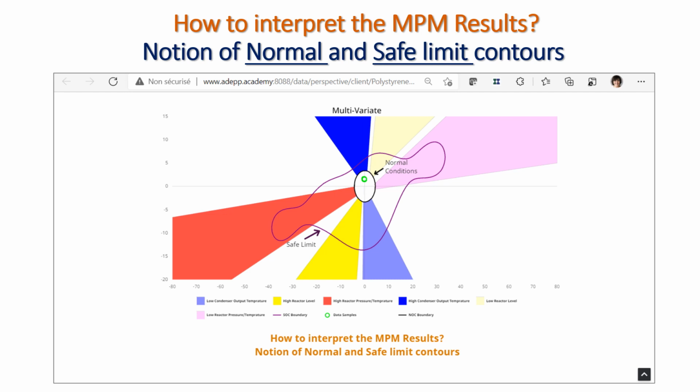In the following slides, the figures are zoomed in and out for a better view. Besides, in some cases, if the number of monitoring variables is high, one may choose to have the projected principal components be 2 or even 3 with accepting less approximation quality, or we may subdivide the main monitoring picture into several two-dimensional pictures.